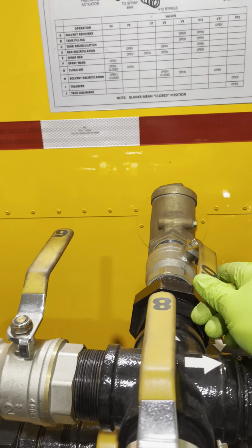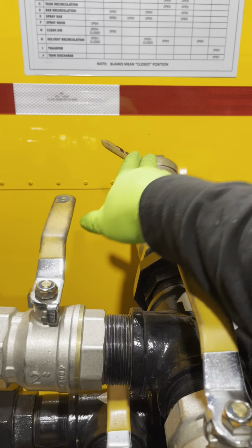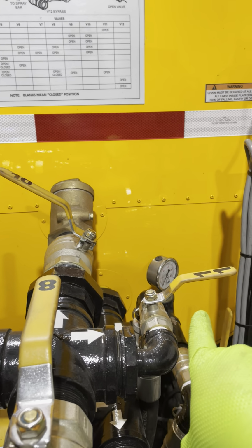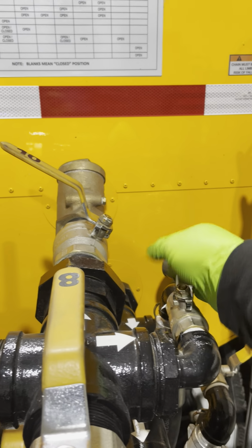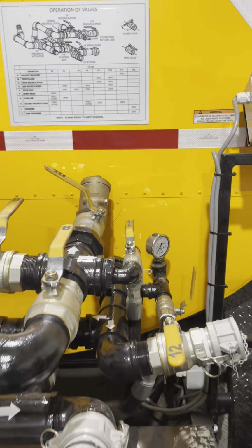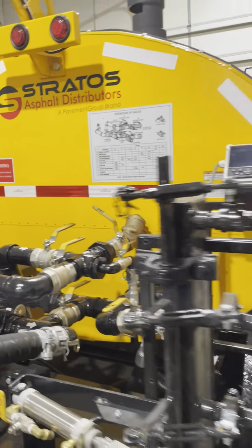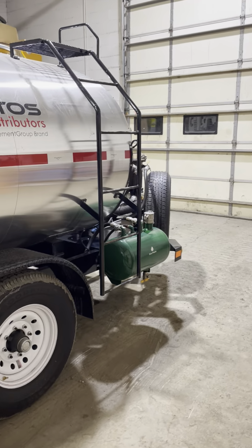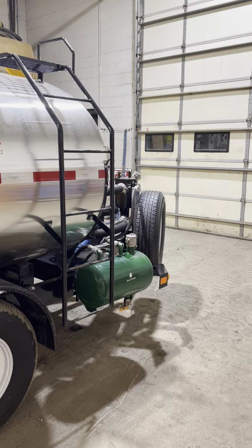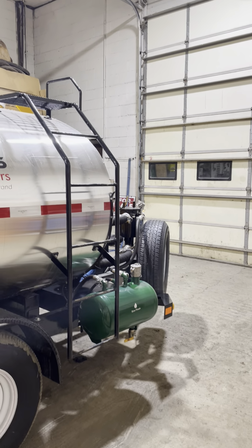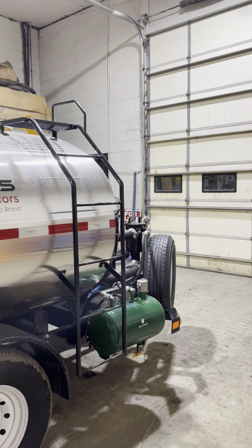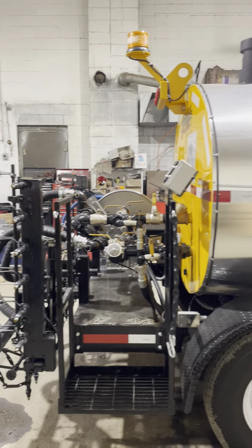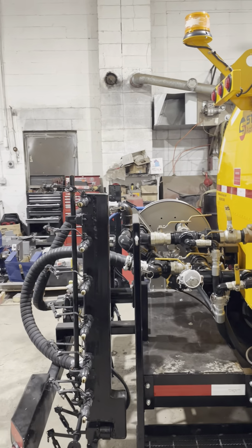Well, we don't want 10 open because we don't want to pump solvent into our tank. So now that it's come across to 8, it's got nowhere to go except, well, here's valve 11, our solvent return line. That's where we want it to return to. So it takes the solvent and brings it right back to the tank. And this is why it's called solvent recirculation. Pulls it from the tank, circulates it through all of the plumbing, the strainer basket, and wherever you direct it to in the back, and fully recirculates.